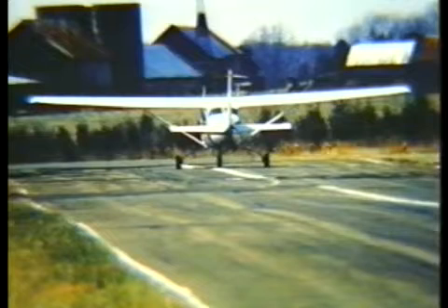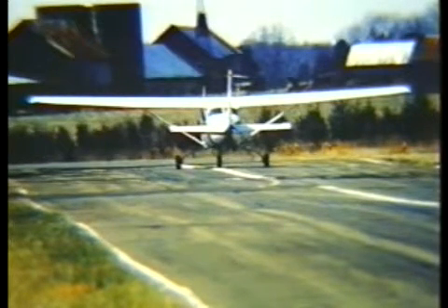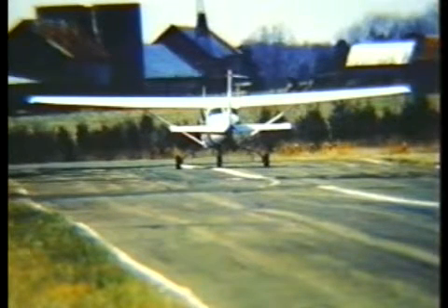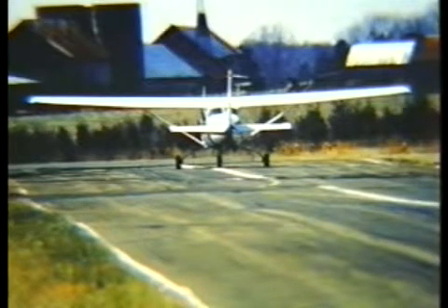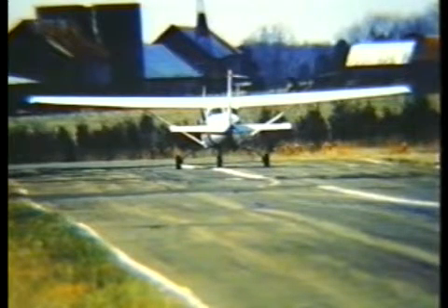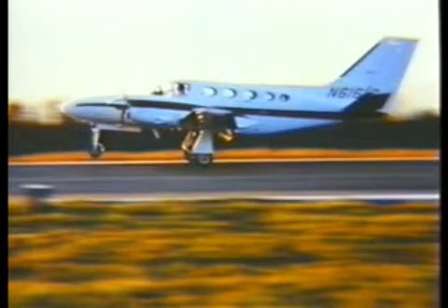You see, a displaced aim point could have you going off the end of the runway at the other end by suckering you into landing long. And since government publications do not provide specific information about non-standard VASIs, it's up to you to know what you're up against. And that completes our discussion of the 8 most common contributors to landing long.